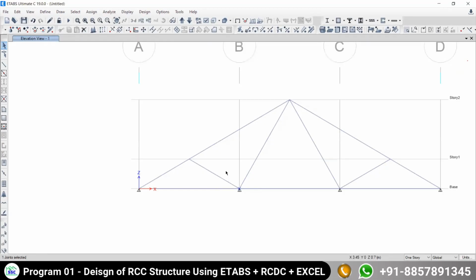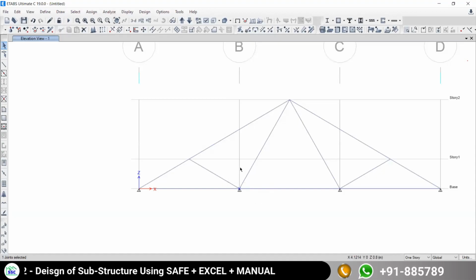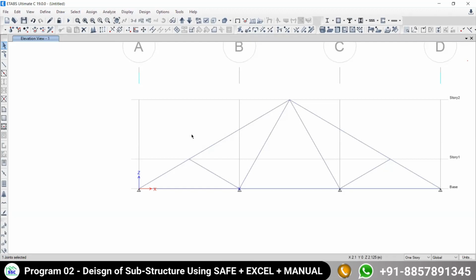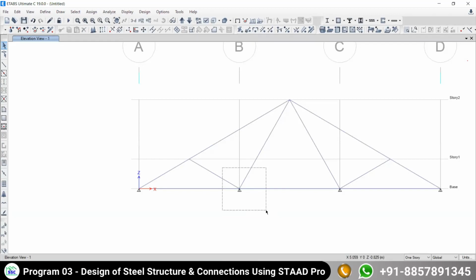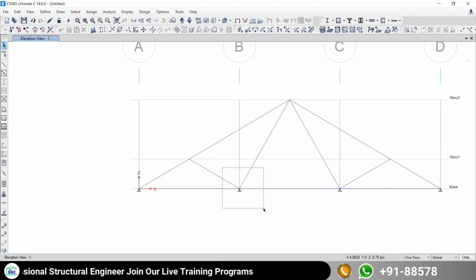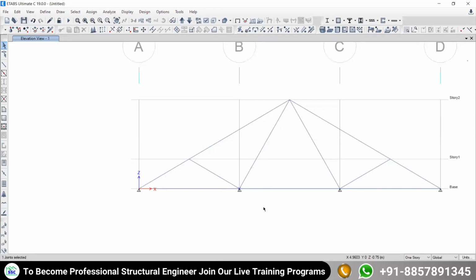So what if I'm dragging from left to right, what thing is going to be completely coming inside of this box? Joint is also one element. Support is there. Support is actually the assignment. Joint is there. So that joint is now selected, one joint.